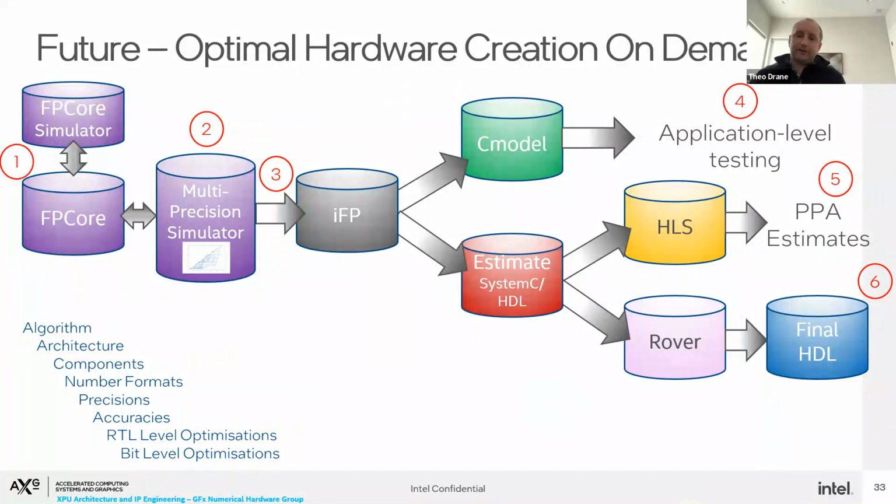And because something like ACL2 can also read in RTL as well, in theory, we can start connecting some of these dots. And it would have to be through a theorem proving process. But even if we park that to one side, essentially we can do consistency equivalence checking between everything on the right-hand side of what IFP is generating.